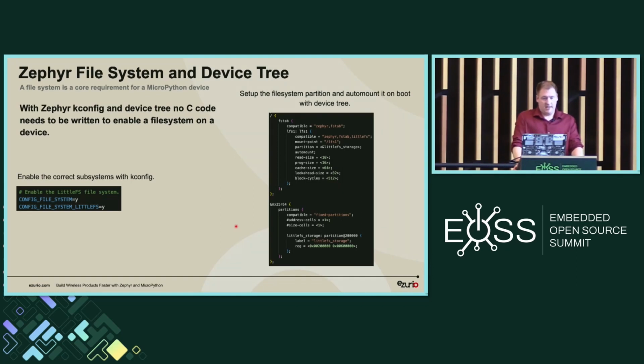So in Zephyr, with Kconfig and device tree, you don't have to write any C code to get a file system running on your board. With Kconfig, turn on the file system and pick what file system you want to use. In this case, we usually always use LittleFS.